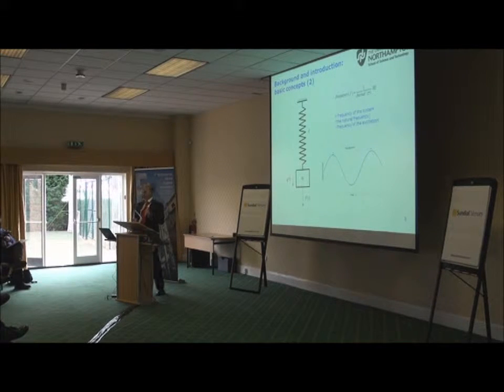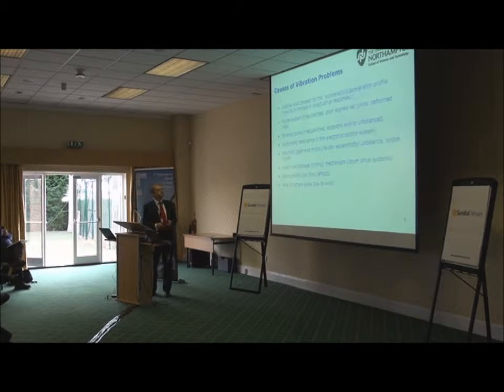And we have two frequencies we need to consider in the system, whether it is lift or escalator, in fact, in any mechanical or electromechanical system. Those are the natural frequency and the frequency of the excitation. The natural frequency is when this mass will vibrate freely without any force applied. When you have, however, a force, like here, and this force is periodic, we need to know the frequency of this force. The problem is when there's a specific relationship between the excitation frequency and the natural frequency.